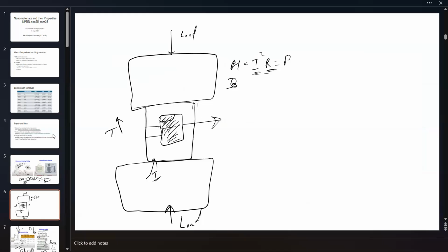Sometimes you don't even have heating elements. You can use graphite dies, and your powder is pressed in between that graphite die, and you pass current through it, current I. And as the current passes through that graphite, you get I square R heating. That will be the power required, and that heating will cause the powder to fuse along with the pressure applied.